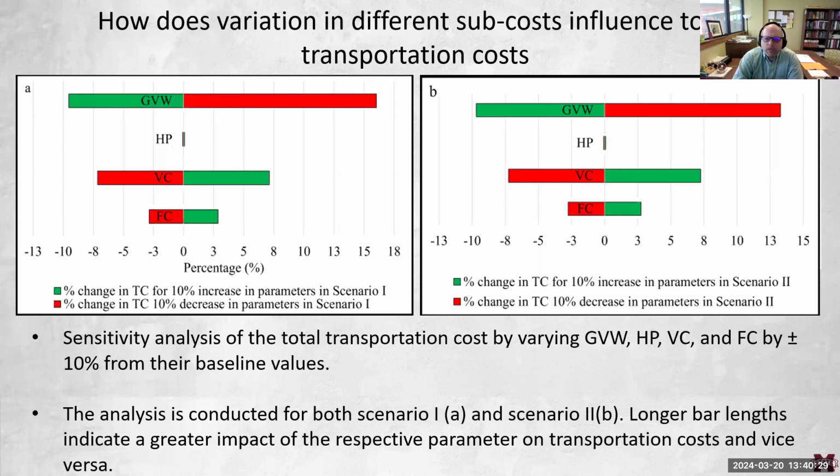And that's interesting because there are many states that are toying with the idea of increasing the overall weight that these trucks could be loaded with. In Mississippi, it's 84 currently. I think they're going to raise it to 88. There are other states that have said they're going to raise theirs, or are considering raising it as a policy option. The problem in Mississippi, and this is more of an anecdote, is that when we spoke with people in some of the counties, we found that they were actually posting some of the bridges even though the bridges had no significant deterioration on them.